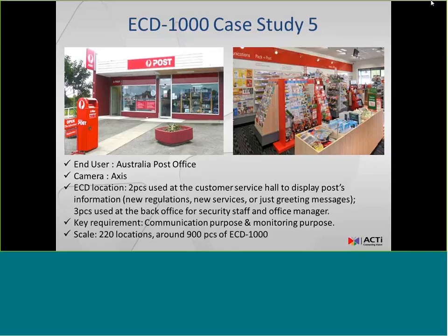In addition, I would like to say that the ECD 1000 has specific connectivity. For example, if I want to have a local view or I want to connect to the ECD 1000 remotely, they have different accessibility. For example, on ECD 1000, we can add cameras, but locally, it should be H.264 compression, and the maximum resolution of the camera of each channel should not exceed 2 megapixels.